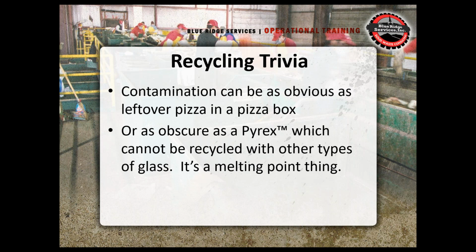If that material breaks and gets thrown in with your regular glass, it can cause problems, because regular glass cullet melts at a certain temperature. When they recycle glass, they melt it and reform other glass products. If you have some Pyrex in there, that material may not melt at the lower temperature that melts other glass.